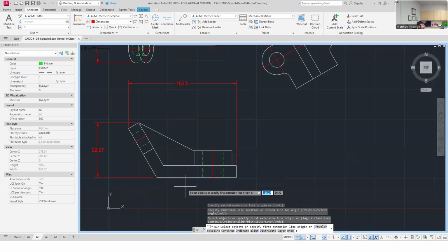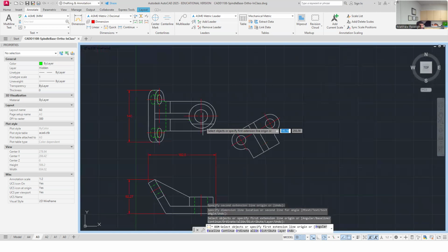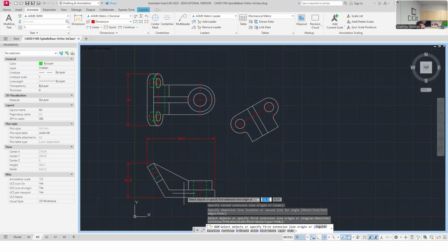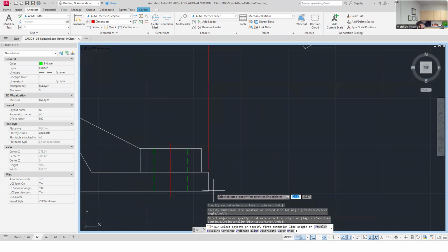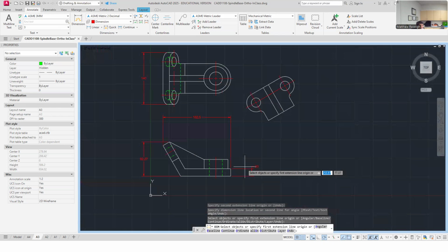So this one here, I think of size, and then location. I'm going to locate it by it sitting on this base, and then I'm going to say that this crosshair is kind of critical. So that's functioning as my location in space. So I just need to worry about its size, and I'm just worried about the side that's flat against the base right here. So it definitely has a thickness here. I'm going to need the thickness of this thing. There's one. I'm going to need the height of that.